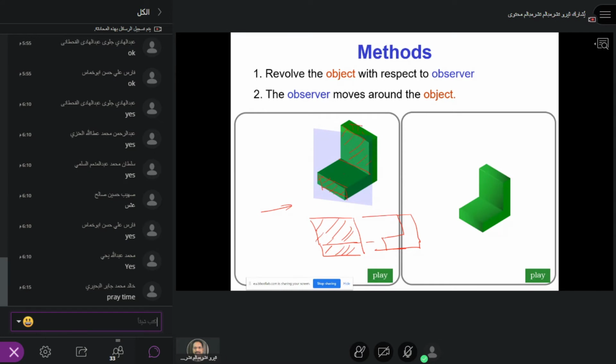When I see from the top view, I can see this surface, yes, but this surface I cannot because it's parallel to my eyes. And this surface I can see. So when I see it from the top view, by using the construction line, I can see the top surface, this one, and this surface. So now it will be a rectangle.